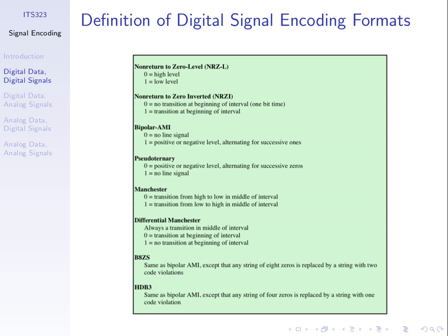After noise, so all right, I haven't drawn the noise in here, but if this is what is received, what are the bits that you've received using bipolar AMI? 0, because it's at 0 volts. 1, because it's a non-zero voltage. Here, here, here, here, here. Something's gone wrong.